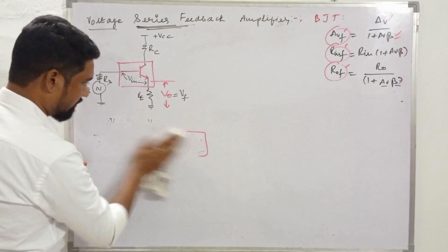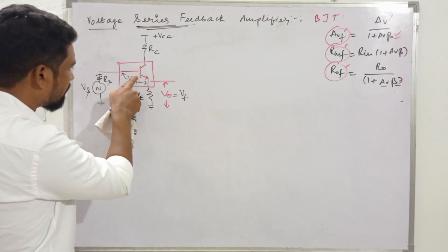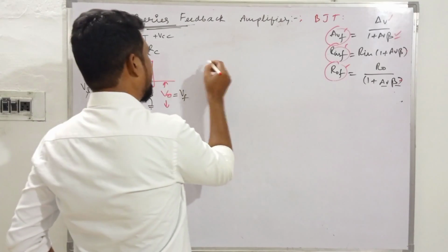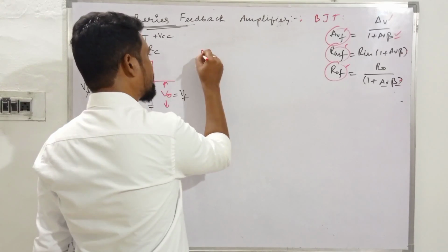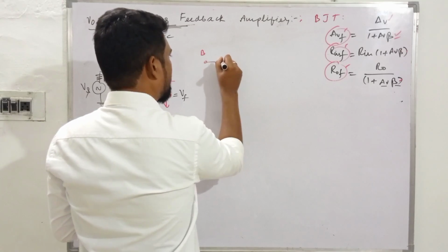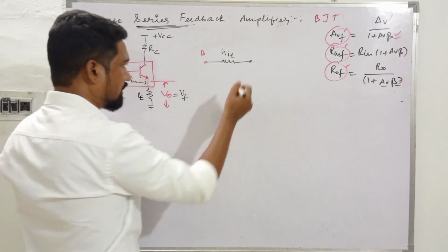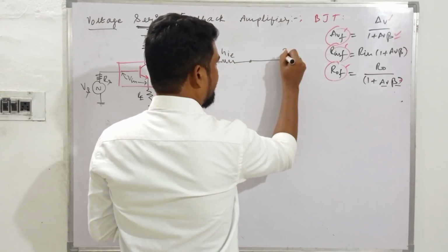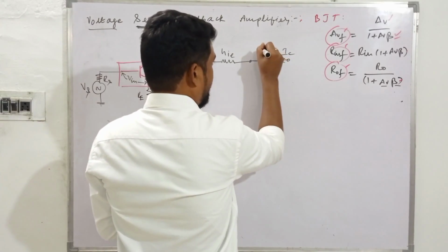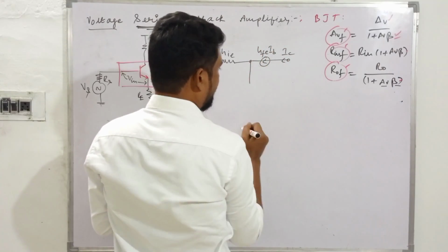So not with this one. Remember, the beta value is unity for this configuration. Not the transistor but the approximate hybrid model. How does that approximate hybrid model look, with the input given to the base here? This is the base. In the base terminal, what do we have in the approximate hybrid model? It's HIE. And the collector over here, with IC, and we have a current generator in the collector terminal, HFE IB, and this is the emitter.